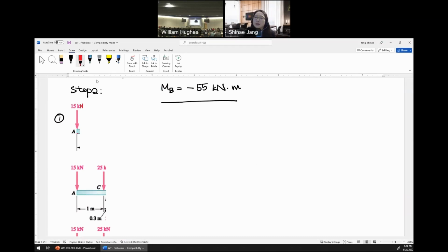And then at the cut section, we add unknown internal forces using the positive direction. I mentioned that we can add N1, but if there are no horizontal external forces, then N1 is 0, so we don't have to consider it. Typically for a beam, horizontal reaction is 0 because there are no horizontal external forces. But if there is, then we need to add it.